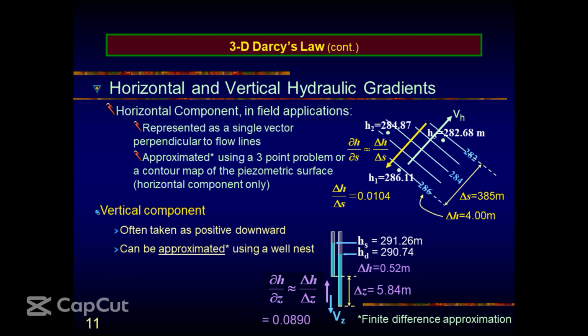So the hydraulic gradient, or the gradient in this case, is now going to be this amount. Although this is the hydraulic gradient, because if you take this minus that, it is going to be negative, isn't it? And the hydraulic gradient is the negative of the gradient, okay? So this gives the hydraulic gradient. Are we following? Which is just simply dividing delta H by delta S.